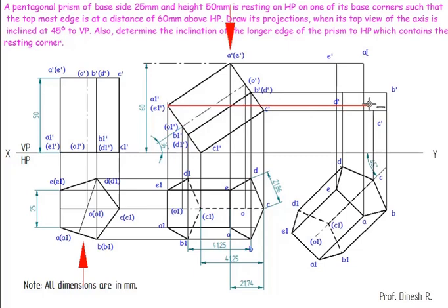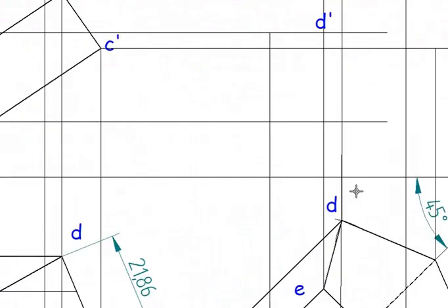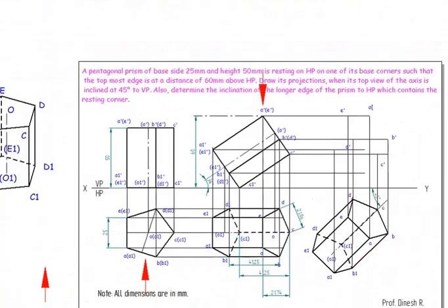Same way, now we are going to go for projecting the bottom face. So this one is A1 dash, E1 dash, then B1 dash. Go for A1 till where A1 is, B1 is to this point, again going for C. C point is at the XY line, D1 is still here, E1 is still this point.